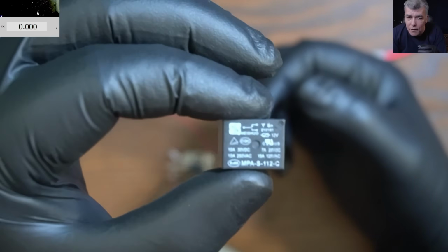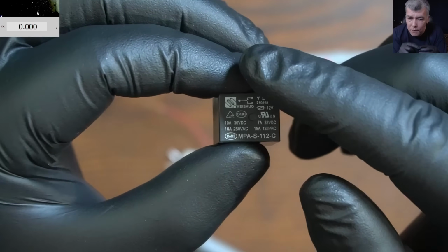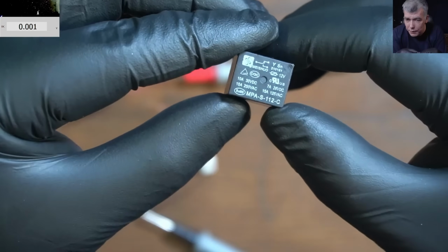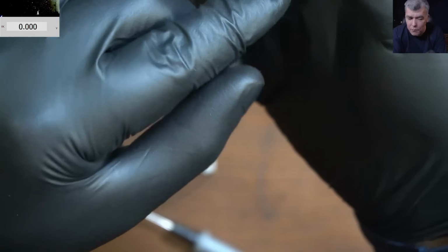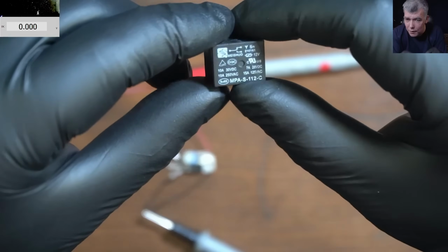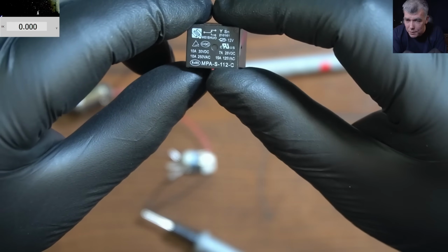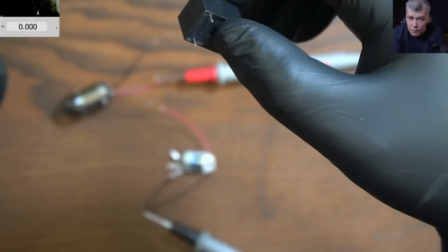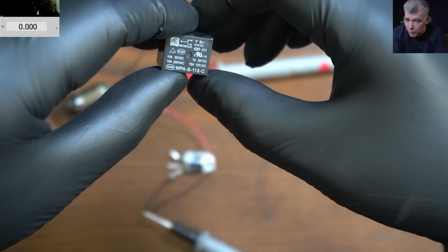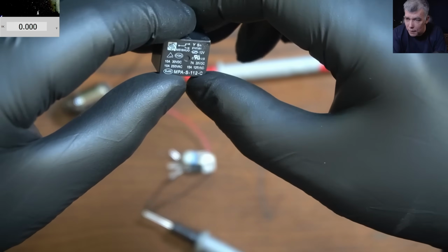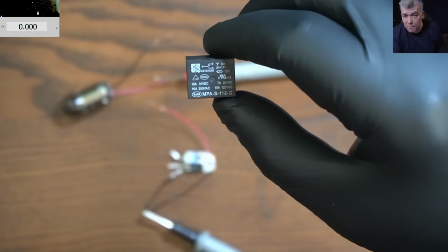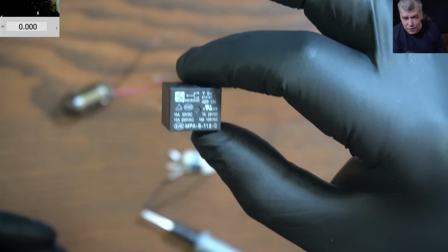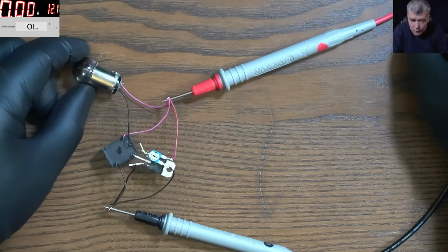In a relay, you have a coil and you have contacts. So it's an electromagnet with contacts. You apply voltage and it clicks and touches two contacts there. This is like 15 amps. So with a small input, probably a few milliamps on the coil, we can trigger up to 15 amps, which is beautiful. The relay is a very nice thing. But the disadvantage is this doesn't amplify anything. It's just a simple on-off device. So it's all done.